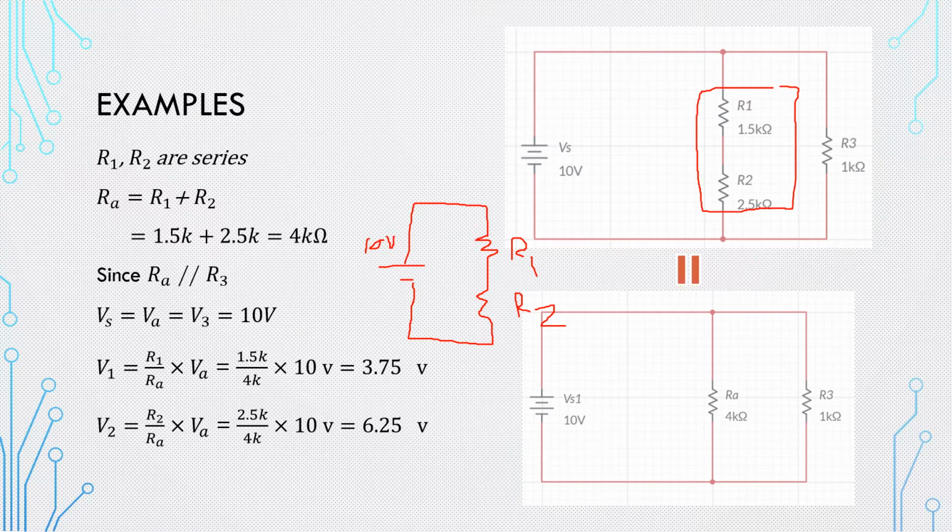So VDR here is going to be applicable for RA, because the voltage I'm going to take is from RA for VA, not the voltage source, although they have the same voltage. But just to keep in mind the procedure, you need to apply VDR for VA, the voltage you supply, or the one that is related to the circuit that you have.